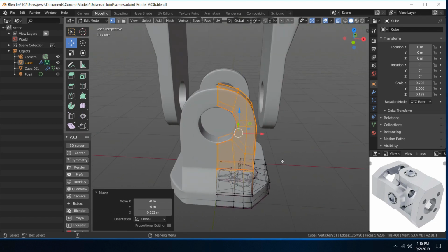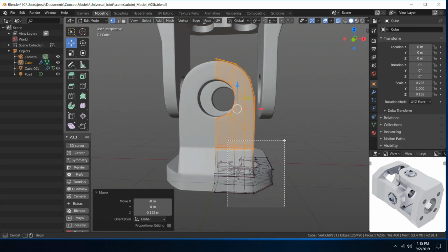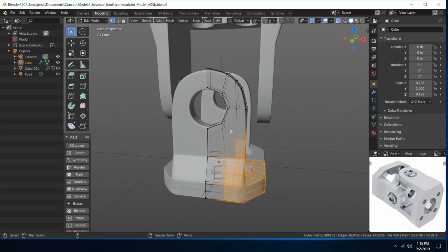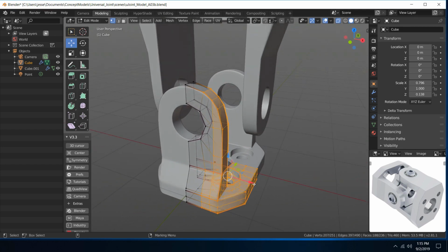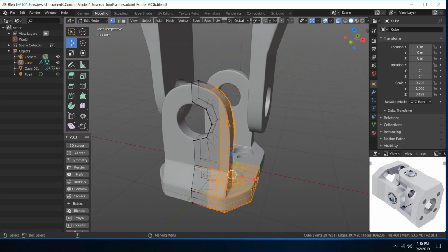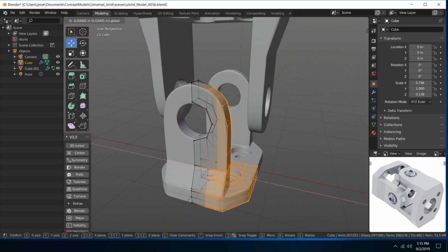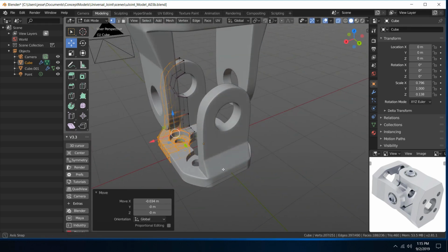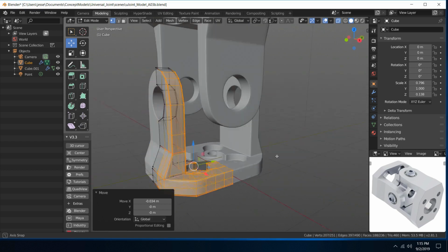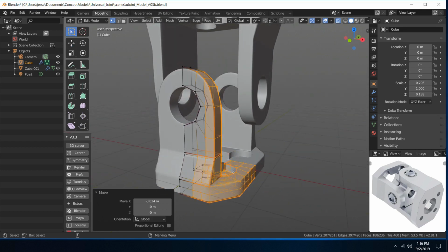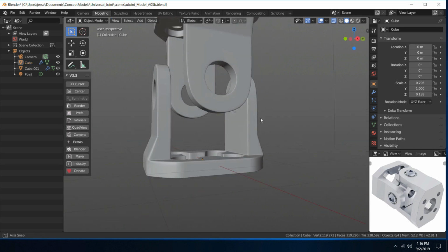So I'm going to go ahead and grab some of these vertices, these outer ones. We want to avoid grabbing the inner where the symmetry is built off of, and also the circle here. Okay, and then we're just selecting the move transform widget, just move these in a little bit. Okay, so I think our proportions are looking better with those changes.